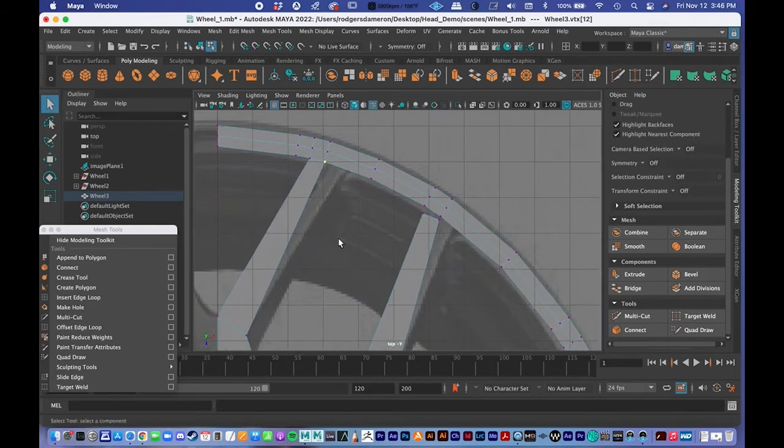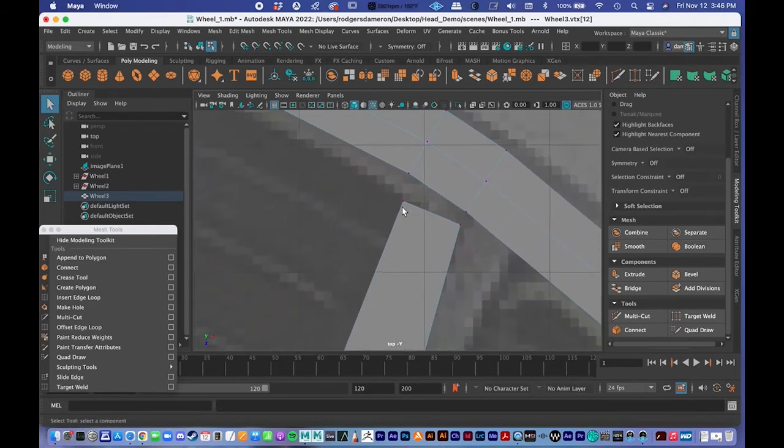So let's work clockwise down the model here. And this goes really quickly once you get used to it. So make sure it's in move mode, right? This vertex that I want to move, hold down V as in vampire. It'll get rounded there in the center. Click the center and then just drag it up and it'll automatically snap to the point. Drag and select the vertex like that. So make sure both vertices are selected there because there's still two vertices right now. And then I'll press that merge button and they will merge together.